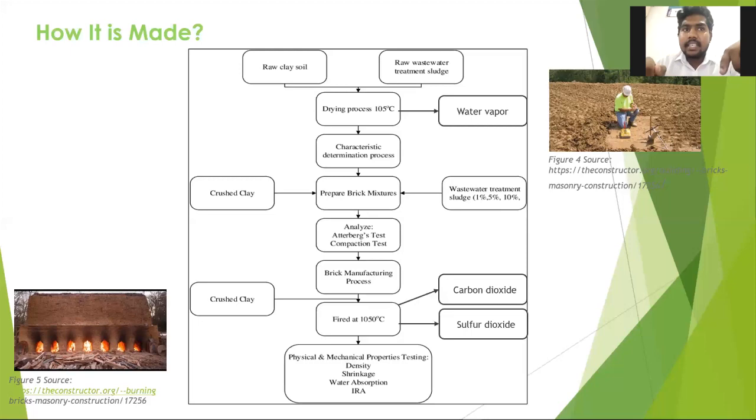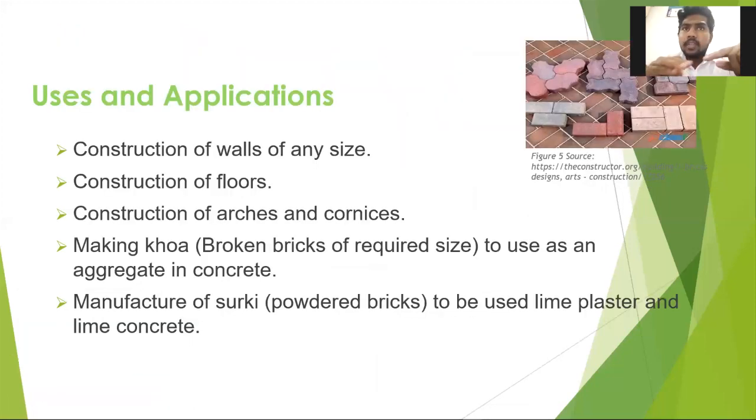We have listed the uses of burnt bricks in point form using some pictures, as you can see in the slide. As you know, burnt bricks are most commonly used in the construction field for buildings and houses, mainly to bind walls. In addition, these bricks are used to construct floors, to construct arches, and to make khoa, which is used as an aggregate in concrete. At last, they are used to manufacture surki, to be used in lime plaster and lime concrete.